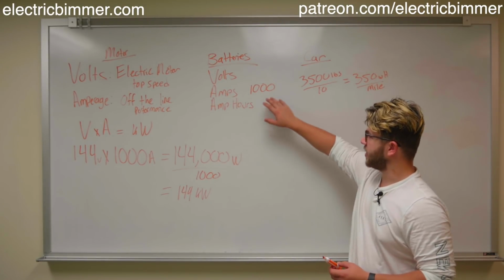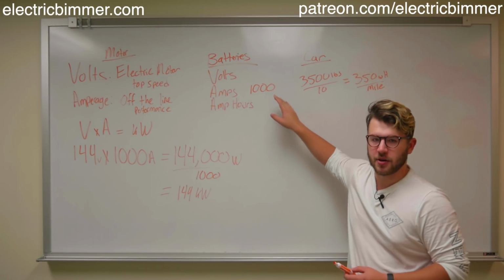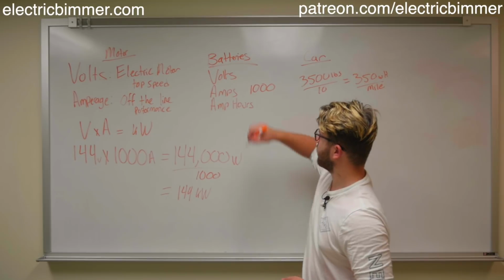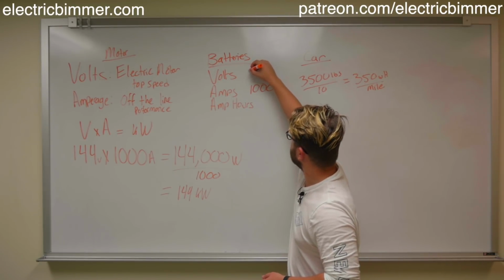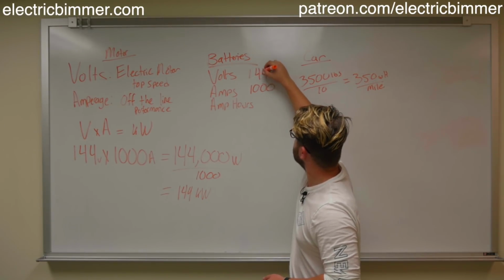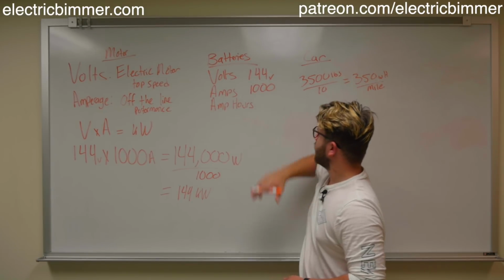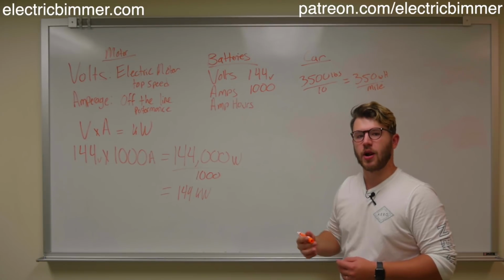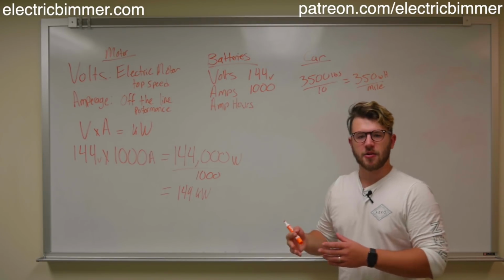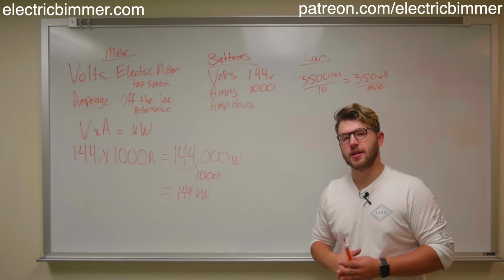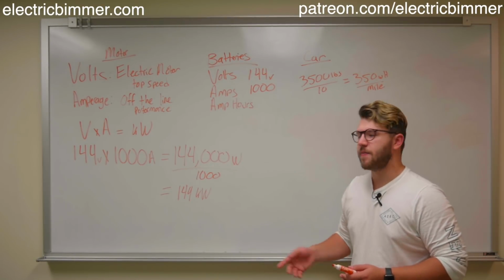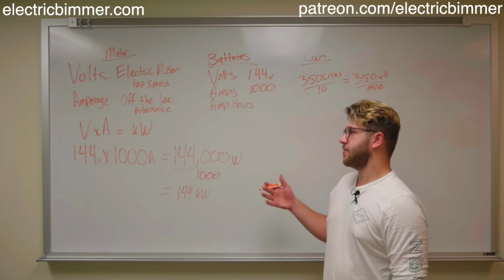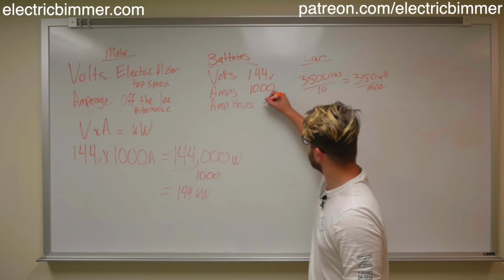So I still plan on doing about 1,000 amps because that's the amperage of the controller I'm looking to get. And as I mentioned before, I have a 144 volt motor. So I'll put 144 up here now, volts. And the amp hours of the pack, I don't think I've necessarily decided on what I want to do yet, but I think to start off with for prototyping, I'm going to use lead acid and then I'm going to move to lithium when I can save up for that. So I don't know, right now if I'm using 12 lead acid batteries, we'll do 12 times 40.